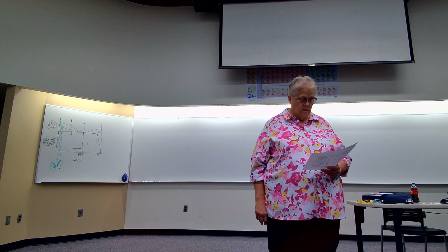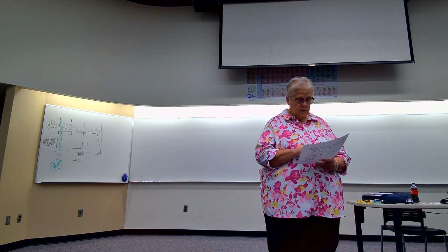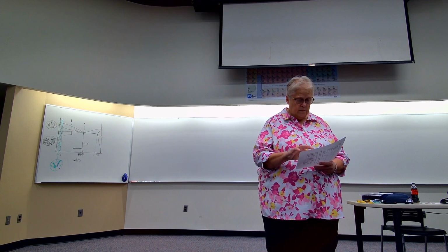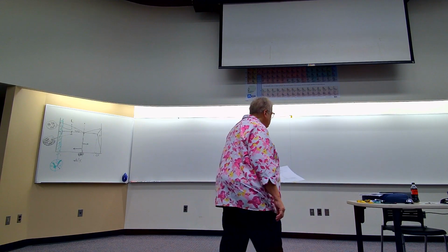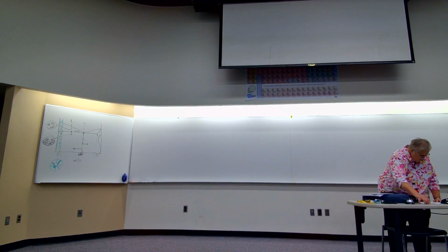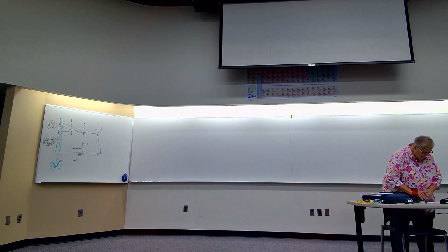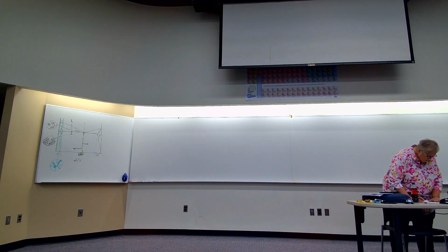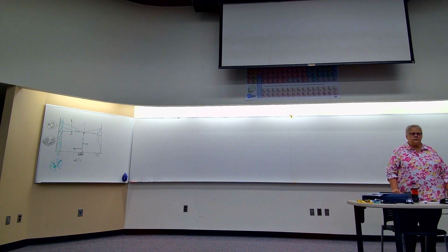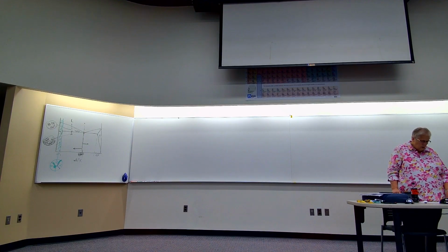Let's say 973, and I wanted to direct you to where the arrow is pointing to eta 2. See where that's pointed, eta 2? So 973, and yeah, 77 weight percent copper. You see that area that I'm sort of pointing toward?